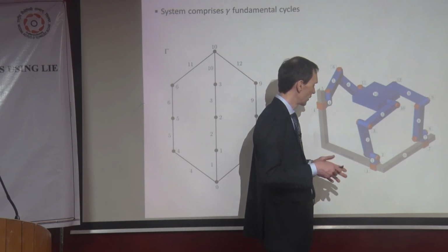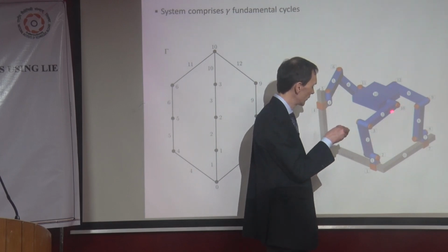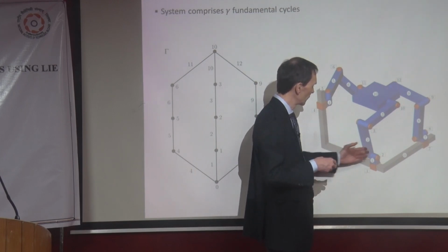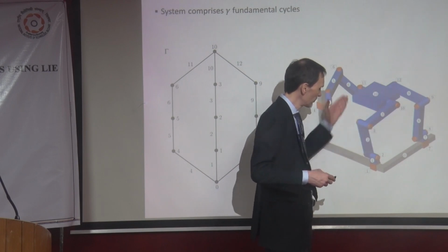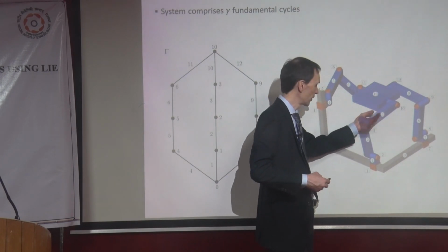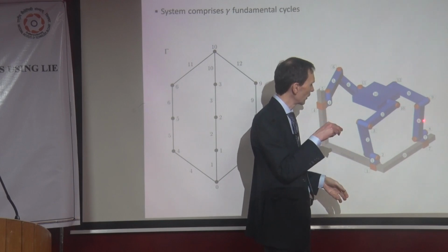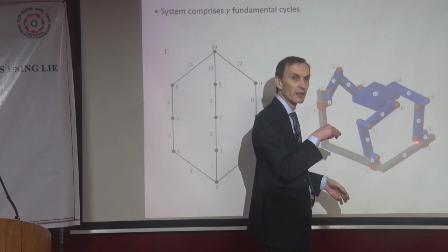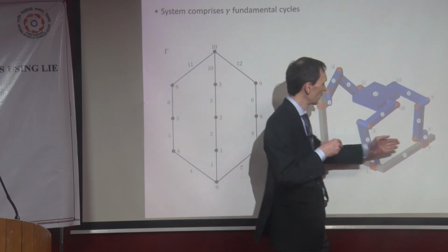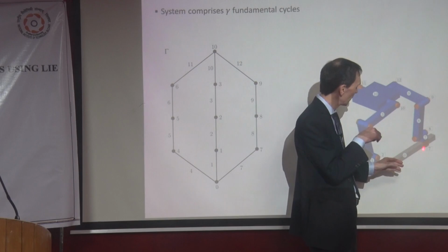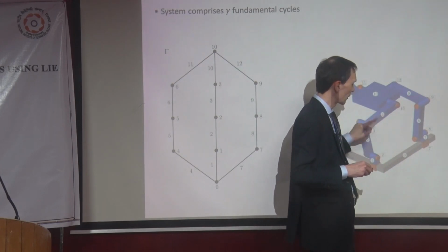So let's say we look at, again, maybe this limb, this is what we had in the other picture. So this could do the planar motion plus the orientation, the rotation about this axis. Now, the rotation about this axis is prohibited by this chain, right? Because this kinematic chain can only perform rotations about that axis.